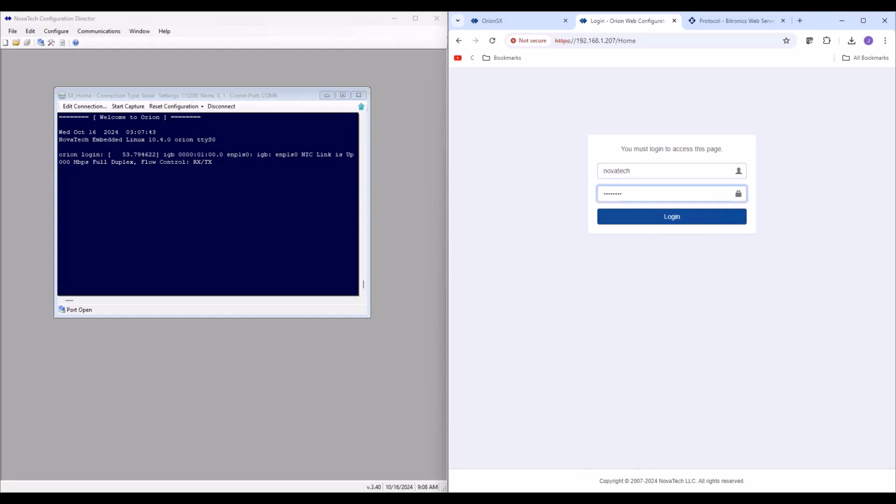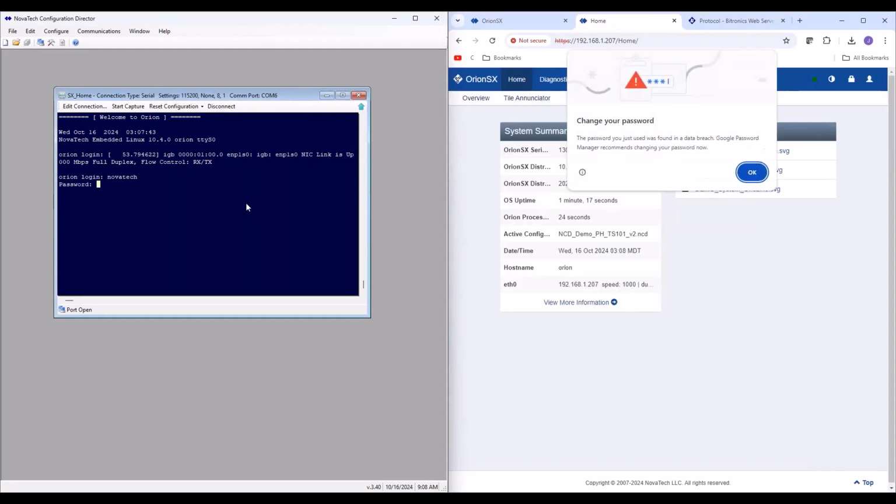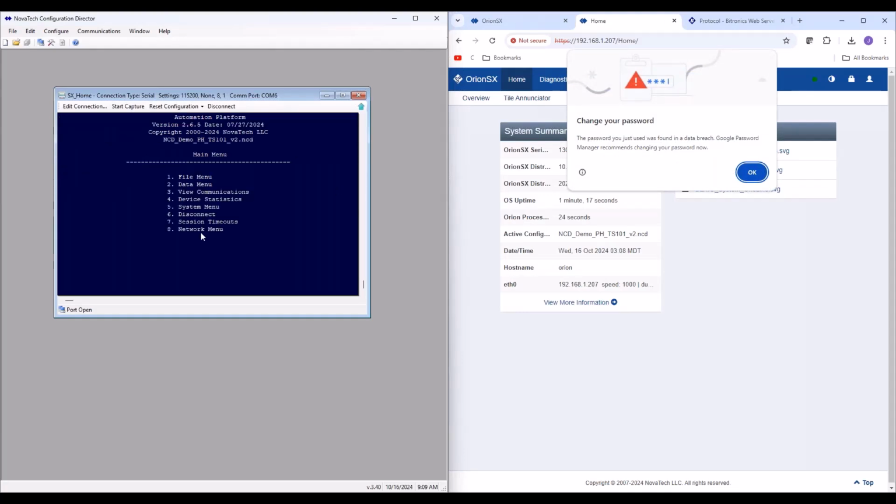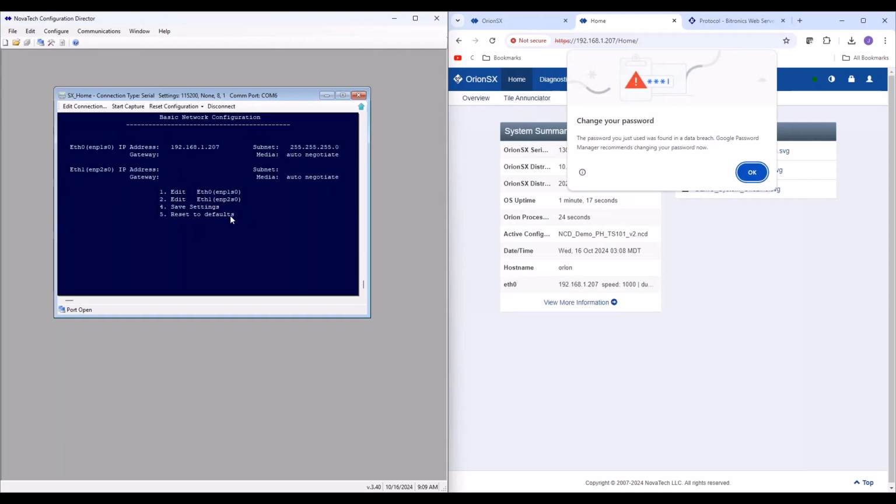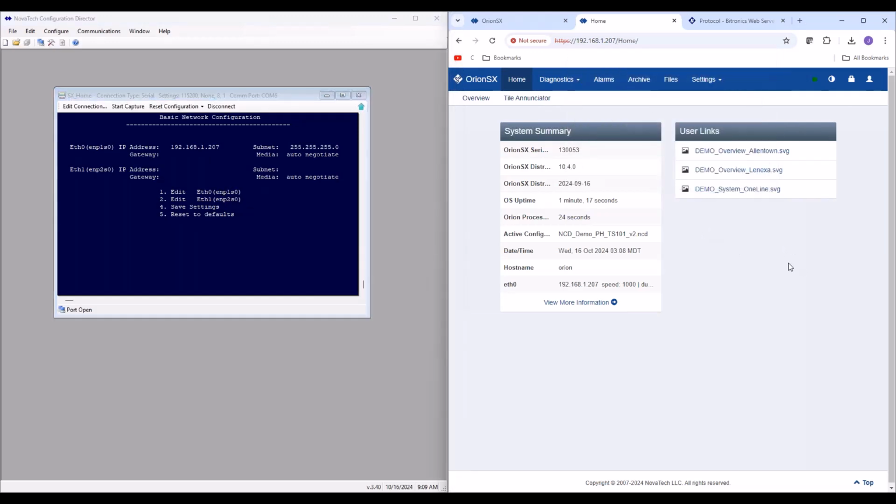The way you fix that is in the MMI, you would have to go back and reset your basic network configuration, which is option number 8. We've covered that in plenty of power hours. So that would be the first step after a wipe to regain access to your web UI. So that is the process of performing a factory wipe.